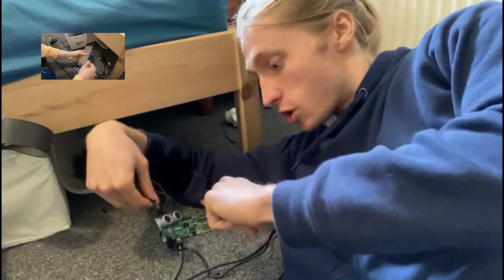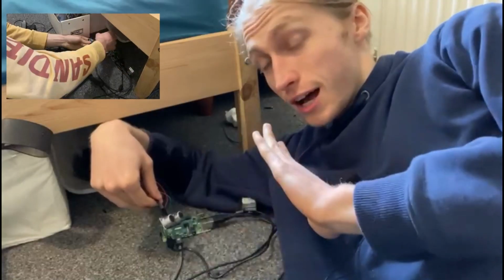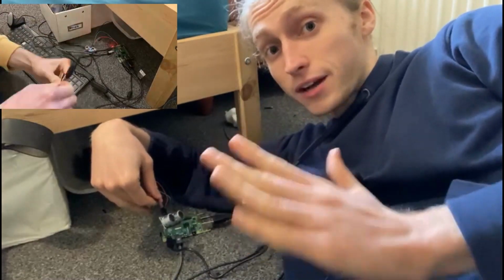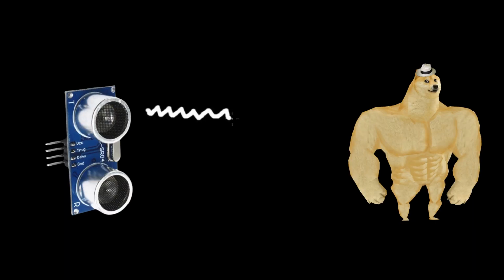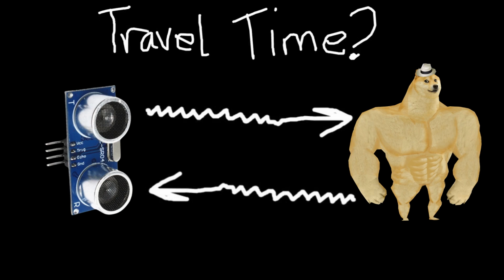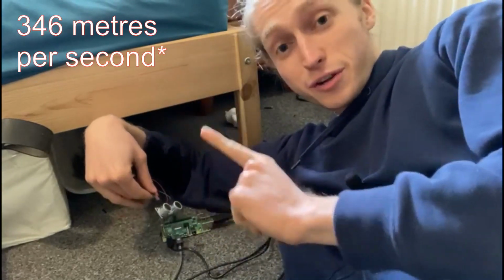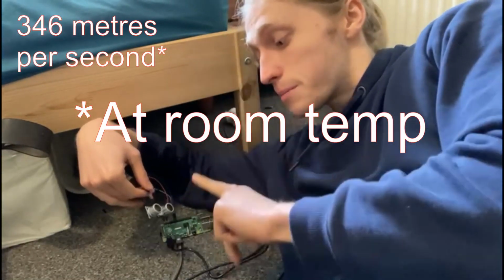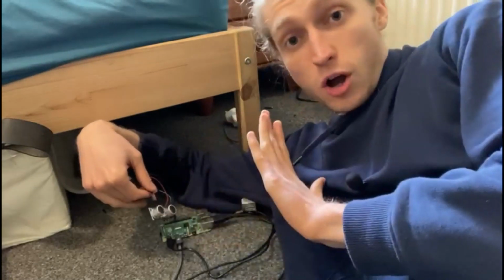Wow guys, look, I dropped my ultrasonic sensor into my controller and it assembled itself. I would never lie about that on the internet. Go away. The way these things work is they send a pulse and they receive that pulse. By knowing the amount of time it took to send and receive the pulse, and that the speed of sound in air is this number here, I forgot it off the top of my head, I'm able to calculate the distance that this thing is from another object.